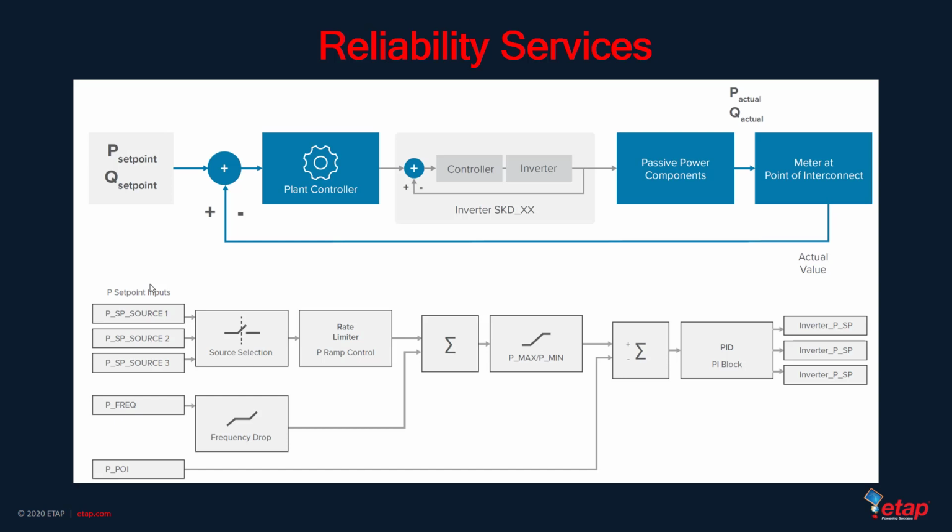The closed-loop nature of the PID loop allows the plant controller to provide partial compensation by increasing the requested set point to all inverters. Inverters which are affected by cloud cover will only be able to produce the power available from their limited irradiance, but other inverters can produce more than their fair share to compensate.